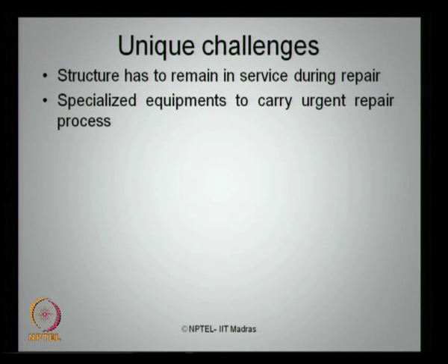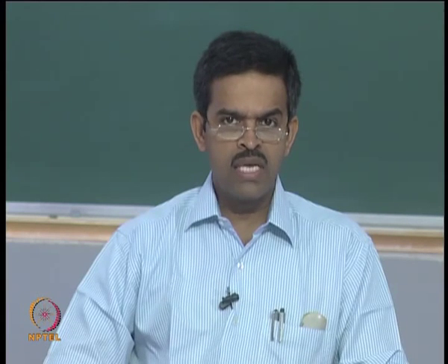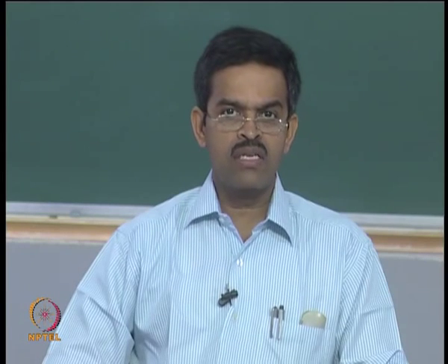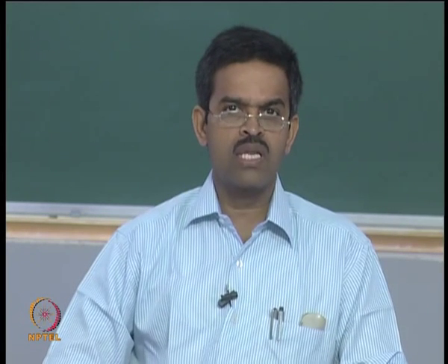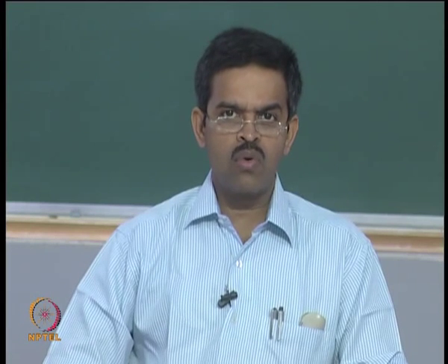Therefore, the load carrying capacity should not be challenged when you are attempting a repair, and hence specialized equipment is generally used, for two reasons. One, you cannot damage the existing structural system to a greater extent, which would affect the load carrying capacity. Two, the shutdown time during which you are going to carry out the repair is always available to you only for a limited period.